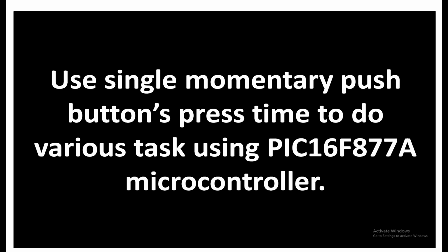We will be using 7 LEDs on a single port, and I will be using a momentary push button. When I press the button, after every 1 second of being pressed, one LED will turn on. As soon as I release the button, for example after 4 seconds, only 4 LEDs will be on, and as soon as I release the button, all the LEDs will turn off. That's how you can perform various tasks. Instead of tasks, I'm going to use the LEDs for demonstration purposes. Later on, you can derive various applications.